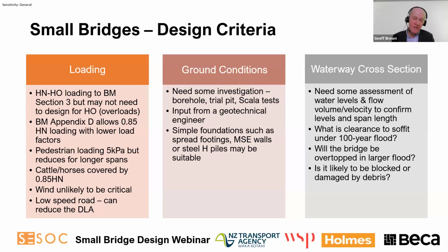Ground conditions, we need to understand the ground that we're building the bridge on. So we need some investigation in the form of either a borehole, a trial pit, or scala tests. We also need input from a geotechnical engineer, or at the very least from an experienced bridge engineer who's got experience of geotechnical engineering as well. The foundations will often be simple, such as spread footings, MSE walls, or steel H-piles, which may be suitable.